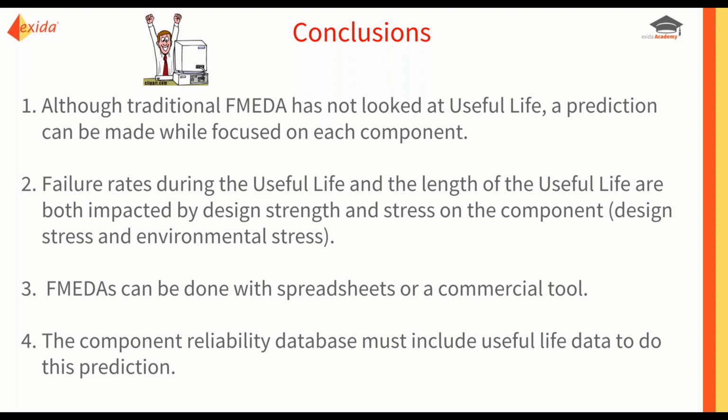Although a traditional FMEDA has never looked at useful life, and I know when I started FMEDAs, I wasn't thinking about it either, it is a perfect place to do a useful life prediction while we're focused on each component in a series system.